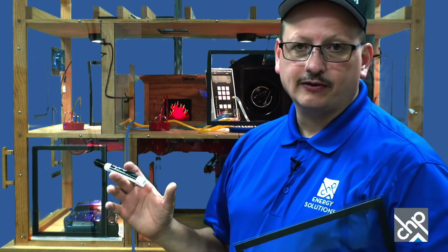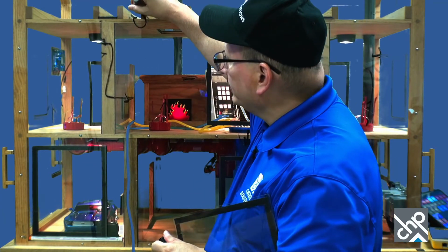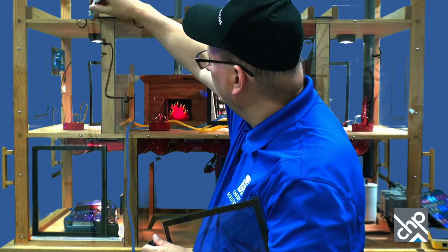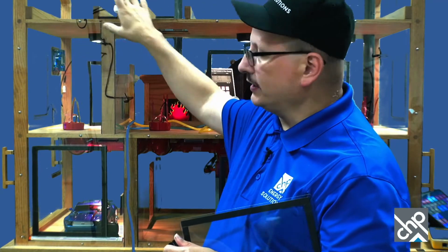They have some that go straight through the wall. They have sound baffles and stuff that you could probably use. Same folks there at Tamarack Technologies. You could also put a grill in the ceiling here, a grill in the ceiling here, and then a jumper duct between them. If you put a duct between them, that way, even when the door's closed, it can go over.